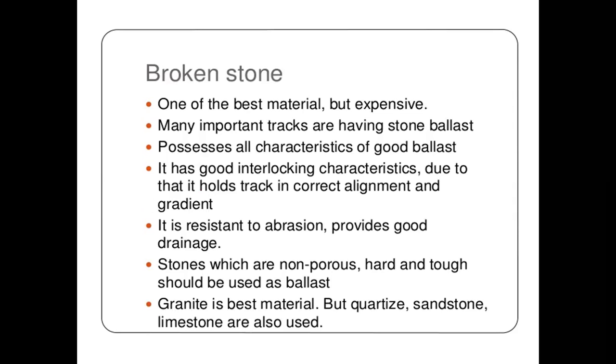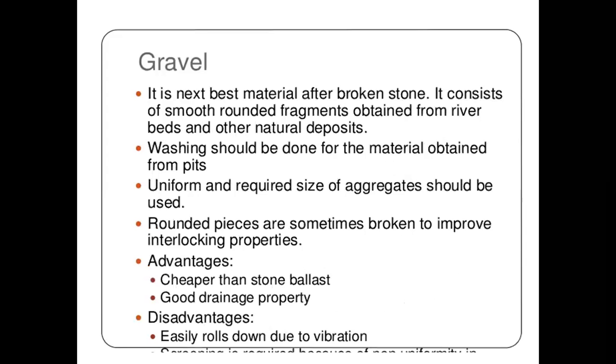Stones which are non-porous, hard and tough should be used as ballast. Granite is the best material, but quartz, sandstone, and limestone are also used as ballast. Broken stone possesses good characteristics of a ballast, but its expensive nature limits its use.